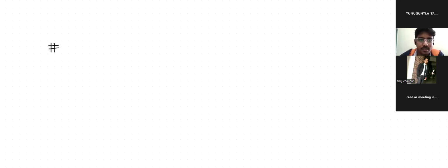Okay. Let's say I am working with some 20 nanometer or 60 nanometer technology. What supply voltage can I give? Does it need to be similar to 1.8, or does it need to be less? No, sir, it needs to be less, I guess. Maybe 0.9 volt. Okay, that's fine. The relation is the important point, whether the value is more or less.